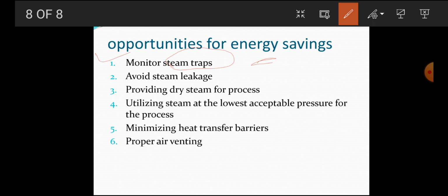An isolating valve is provided in the downstream of a trap and a test valve shall be provided in the trap discharge. When the steam valve is open, condensate discharge and flash steam are required to be observed. So we need to observe this steam trap, the condensate discharge. Inverted bucket and thermodynamic disc traps should have intermittent condensate discharge, meaning in between there should be a discharge.